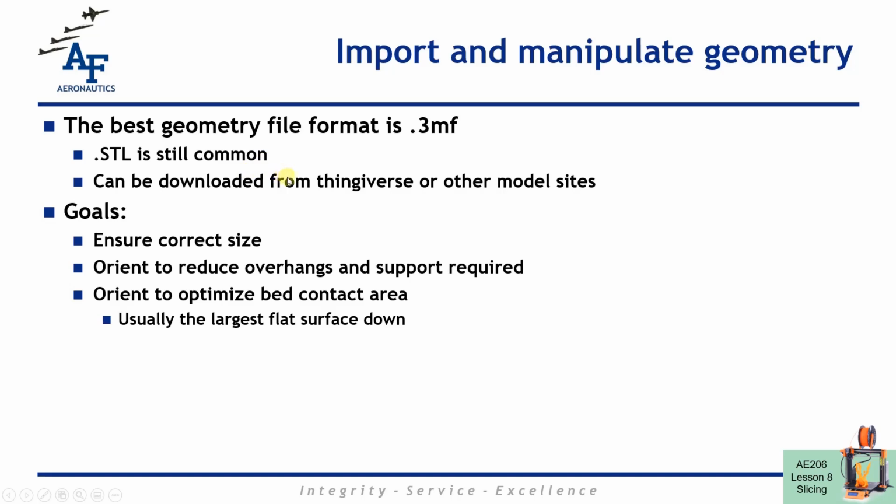But if you export a model from Fusion 360, you need to make sure you're exporting a 3MF file. And the other thing about a 3MF file is Prusa can actually save all of the slicing settings in a 3MF file. So you can have a 3MF file where it's just your geometry that you exported from Fusion 360, and you can also have a 3MF file where it is the geometry in the right orientation with the right slicing settings to generate a G-code file to send to the Prusa printer.